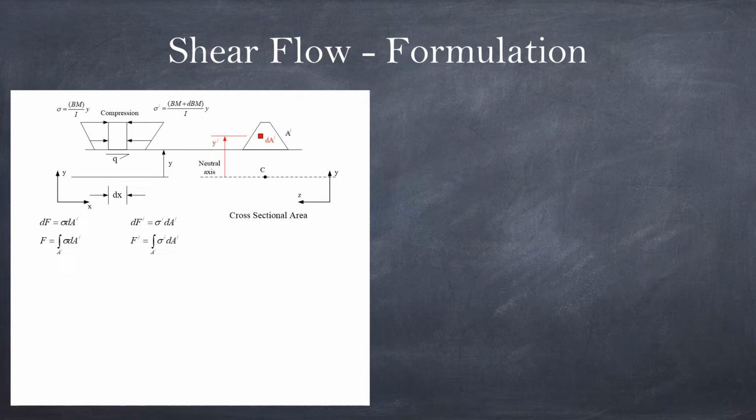Right. So the next step is set up the same way we set up for the shear stress. However, the difference is that although we derive the force from sigma and sigma prime the same way, the force from the shear flow is not the shear stress. So therefore, we don't multiply by the total area. We just multiply by the length along the beam, which in this case, the element has the length only dx. So the force for shear flow is q times dx, the little q.